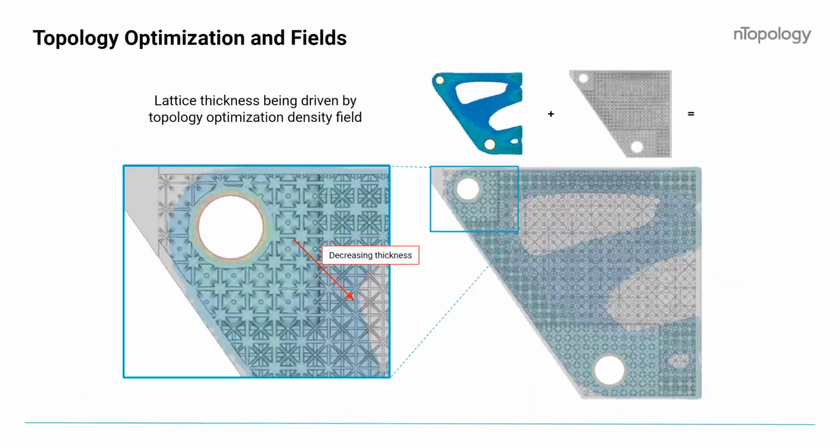This example here is just driving home this idea. If you think of topology optimization and the density field that comes out of it, on a basic part like shown here on the screen, you start with that image, your thresholded element densities there, and the picture on the right is showing just the original part, but in this case, as a demonstration, we shelled it and filled it with a lattice structure. Because fields are such a native type in the system, you can extract that directly from the topology optimization, and if it made sense in your application, you could use that field to modulate geometry directly.